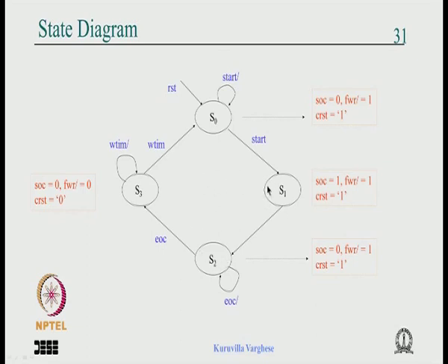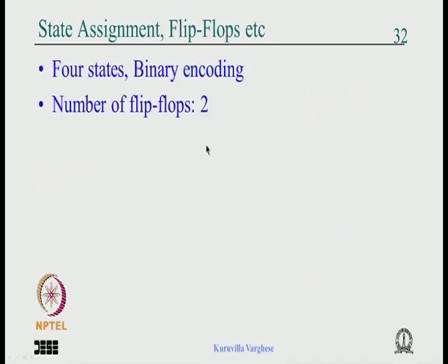It is very dangerous. Luckily we have only 4 states and 2 flip flops, but assume that we have, say, 6 states, then we need to use 3 flip flops and there are 8 states, so there will be some unused states. If you power it on without a reset, and it goes to some unused state, we do not even know the behavior of the state machine, very dangerous. So it has to be properly reset. That is what we are going to see, so let us look at that.